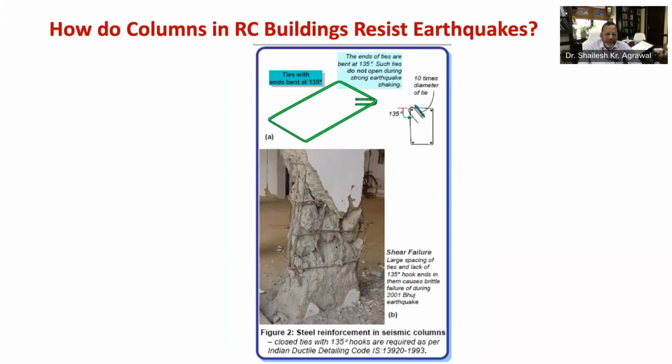Designing of column involves selection of material to be used, that is grade of concrete and steel bars, size and shape of cross-section of columns, and amount and distribution of steel reinforcement. Selection of material and size, shape of column are part of overall design strategy of the whole building.